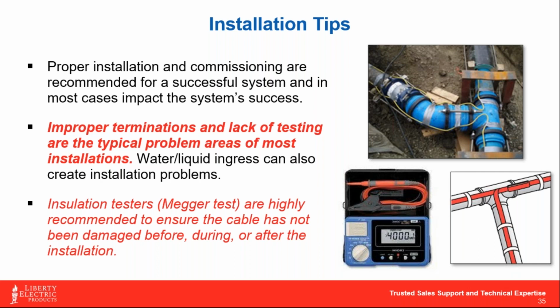And then before you spend a lot of money to insulate over the top of that pipe, we can address the issue, versus everything's on, you paid big money for ceramic insulation or something like that over the top of these pipes, you flip on your circuits and find out you got a fault on one of them, and it was due to the cable being damaged because it got pulled across a burr, something to that extent. So if the installer is measuring on a regular basis, he can easily uncover any sort of damage to that cable before we get too far down the line.